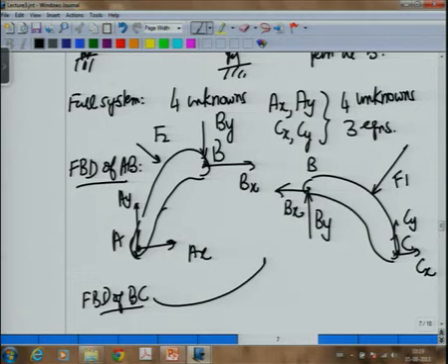So, internally you can say this is a statically determinate system, whereas externally if you look at the total system, it may be indeterminate. So, that is how these things work. And sometimes, we are talking of cases where the unknowns were more. What happens if you have more equations? If you have more equations, then what will happen, as we will see in the example, either one of them is trivially satisfied, that 0 is equal to 0. You will get something like that, which would mean that even though the system can move along that axis, the forces are acting on it such that there is no movement, and that is why it is in statics.